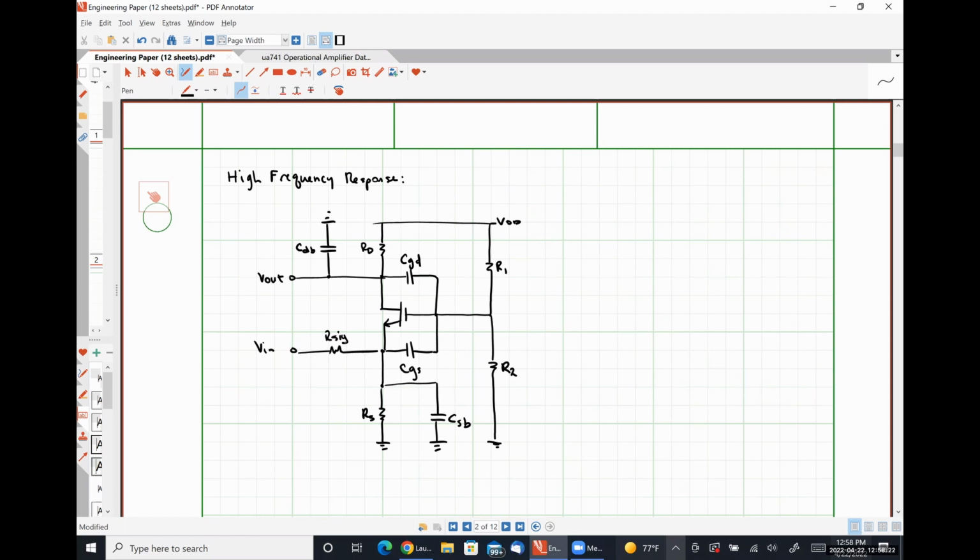So just to be clear here, our capacitor Cin that we had in the previous example, we are now at a frequency high enough to where that capacitor appears like a short circuit. We are now in the range of frequencies at which the internal parasitic capacitances of the MOSFET are beginning to influence the behavior of our circuit.